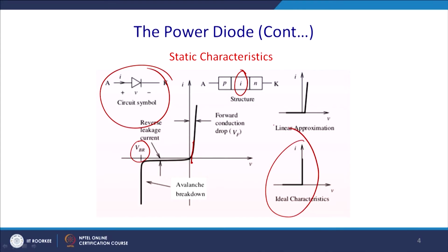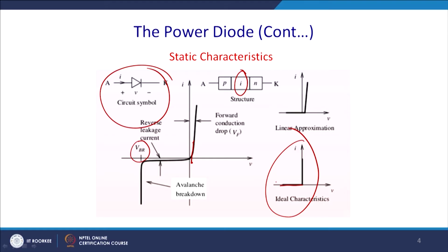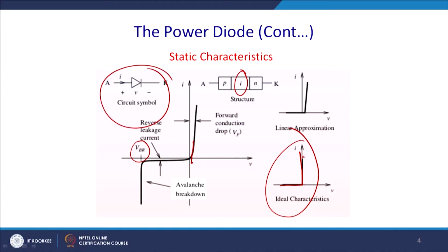And this is actually the ideal switching characteristic. A diode essentially is an uncontrolled device. It has reverse blocking capability, which is shown by this line, and it will conduct in the forward region. This is the mode of operation. It does not have forward blocking capability or reverse current flow capability. So, it has forward conduction capability and reverse blocking capability. This is the characteristic of the diode. Anywhere you require this kind of characteristic, you can suitably place a diode instead of any controlled switch.